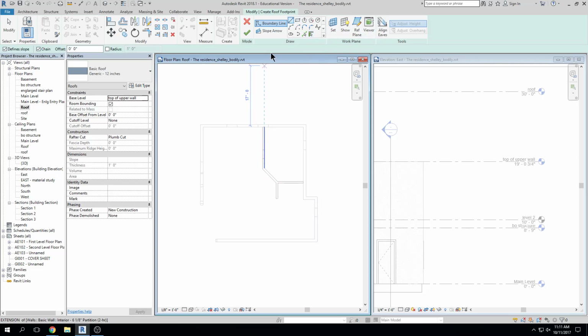Great. If I wanted to have an overhang, I would need to remember that I have an offset option over here. Let's do 4 foot, enter, okay? So now anything that I draw, like if I use the pick line, right, I get a 4 foot offset. So click, click, it's magical, right, click, click.